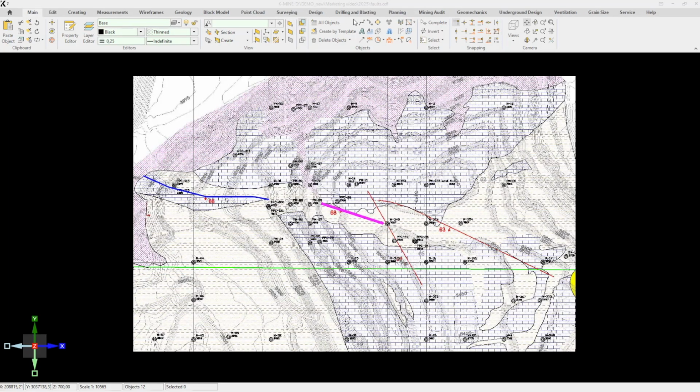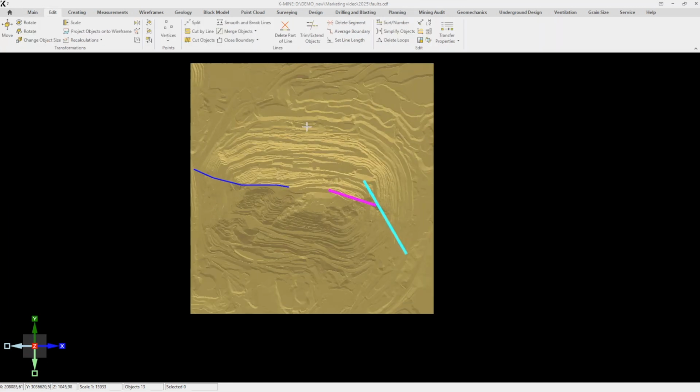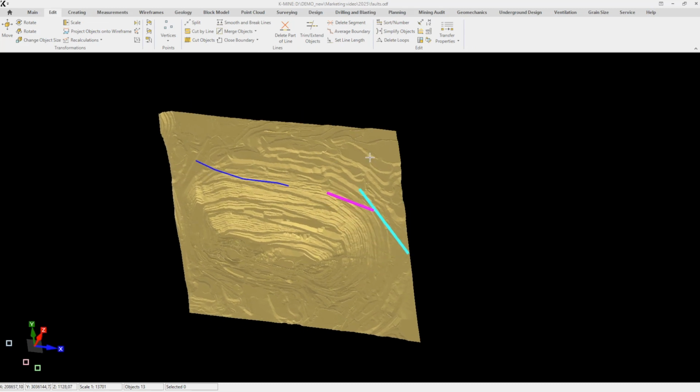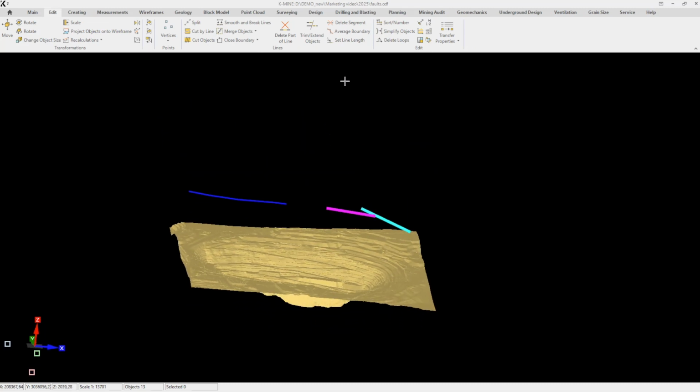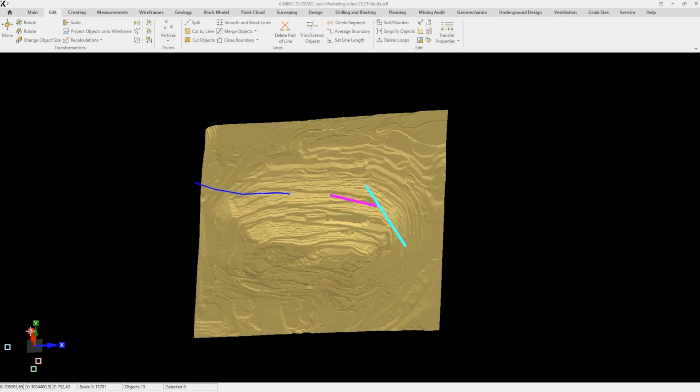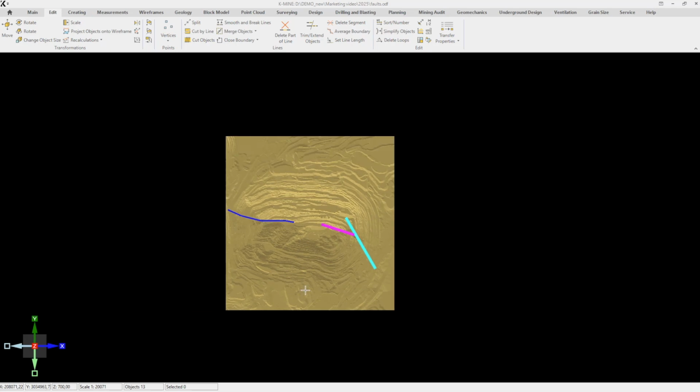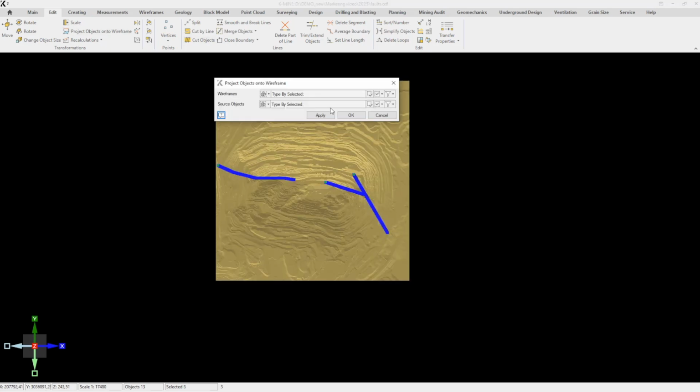The new fault system modeling feature allows you to quickly create framework models of faults and their systems. For example, on the map, we can see several fault traces at the surface, and their dip and strike elements are known. We can draw these lines in plan view, then project them onto the specified surface to assign each point its absolute z coordinate.